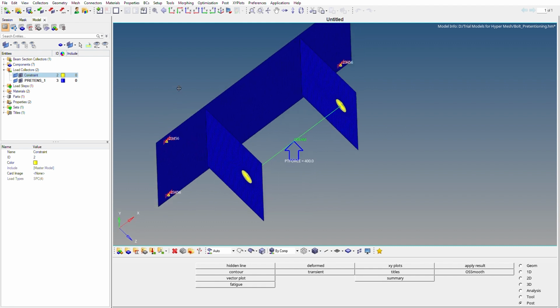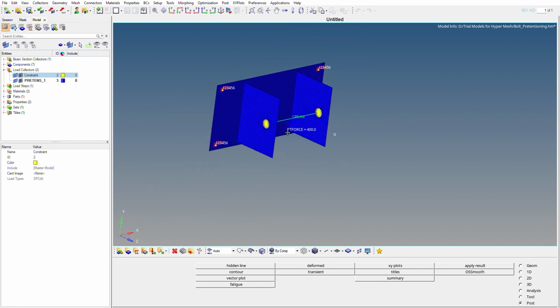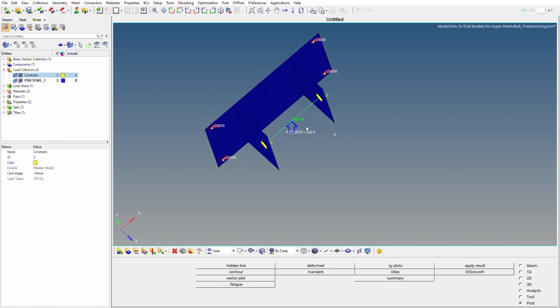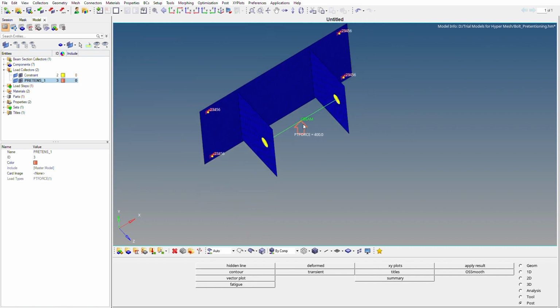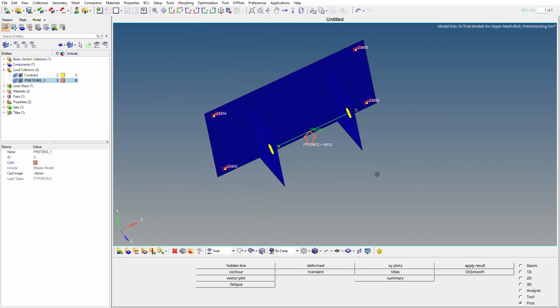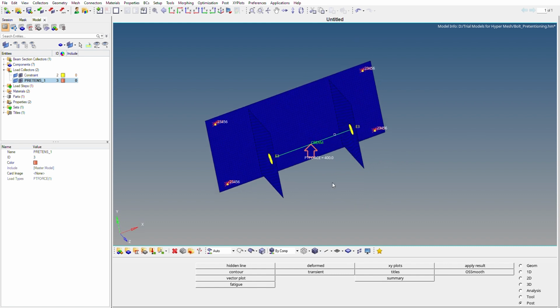Okay, so you can see the load will be applied something like this. You can see it here. So okay, I'll just change the color just in case if you're unable to see it properly. Okay, so you can see it here. I've put it in orange color, right? So basically now we have the meshed model, right, with the materials and properties applied, and we have created the constraint, we have applied the load, right? So what is the next step?